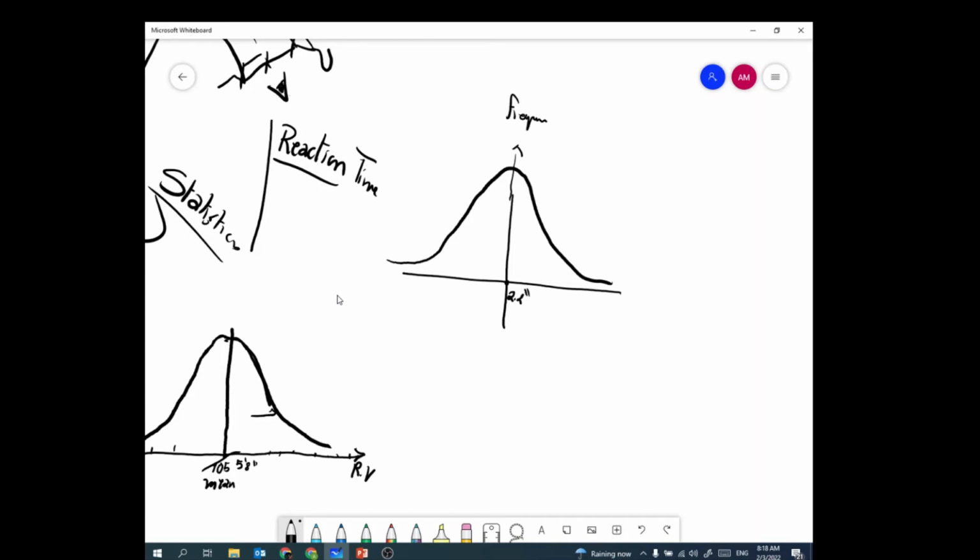However, we have people who are very, very fast in their reaction time, but much, much fewer compared to the rest of the population. For example, a baseball player or a goalkeeper has a shorter reaction time, so they can excel in their sports. And we have people who are a little bit slower. When we want to pick a number that will capture everyone in my driving population, I cannot use all these values. I cannot say 100%. I will never reach a number. Should I make it 10 seconds? It will make the design of my highway really bad.